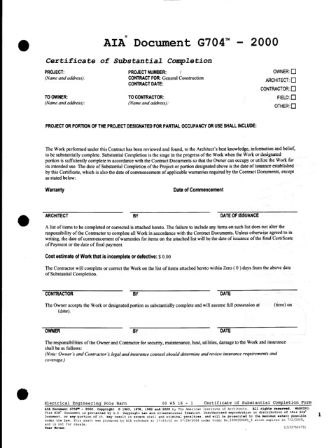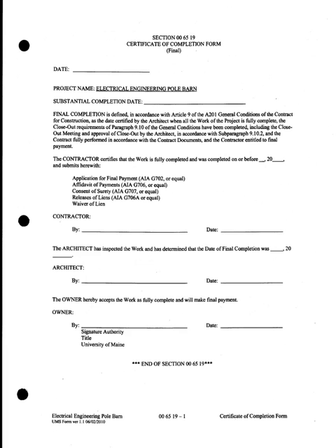Contract changes again are listed here. Certificate of substantial completion. When the job is almost done and occupiable even, we want a certificate of substantial completion that says the architects looked at it, the contractors looked at it, the owners signed off, and we are substantially complete. Doesn't mean it's totally done. We still got that retainage, but it's something they need to make sure is taken care of.